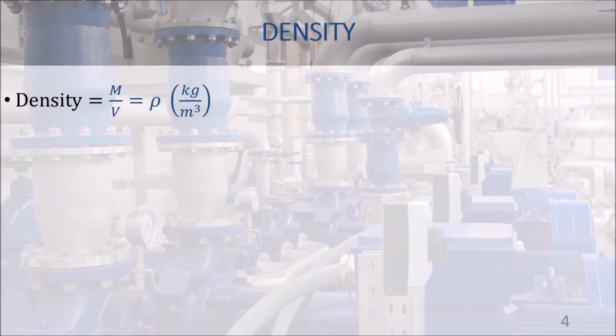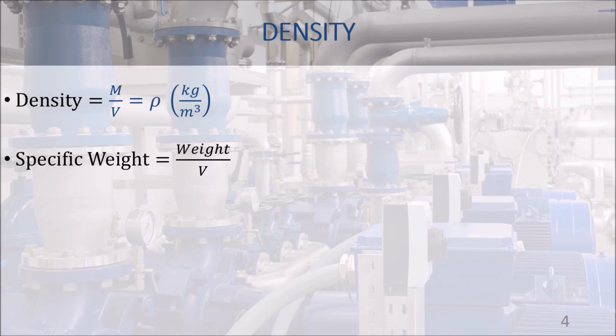The density of a liquid is how many kilograms there are in a 1 meter cube tank of this liquid. We will denote density by rho and give it the units kilogram per meter cube. Two properties are derived from density. The specific weight gamma is how heavy 1 meter cube of the liquid is. It is simply the density multiplied by gravitational acceleration.